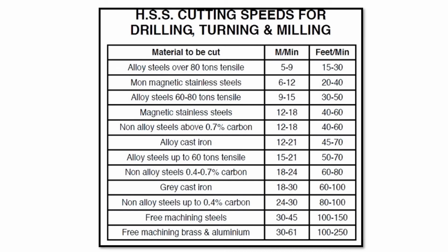Here's an example of recommended cutting speeds for high-speed steel tools for various materials. This is a generic table. Make sure that you get a copy of the recommended surface speeds from your tooling supplier. And of course, we can reference recommended surface speeds for different cutting tool alloys from the Machinery's Handbook, if you have a copy.